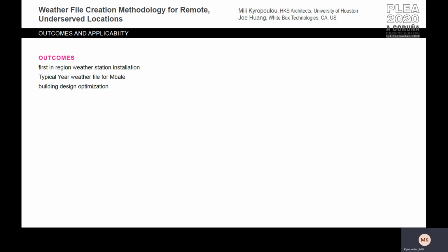Calibration of reanalysis models using only summary data that cover most of the climate variations, with focus on the rainy and dry season, produced a reliable weather file of sufficient accuracy for design purposes. This was mostly possible since the climate variations during the year are minimal in a location right at the equator. The methodology of calibrating reanalysis data using summary measured data can be applied in other locations as well. Attention, though, must be paid to the proper installation of the weather station and the seasonal climate variations.